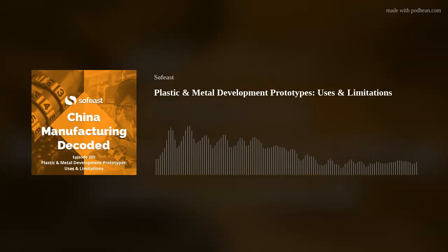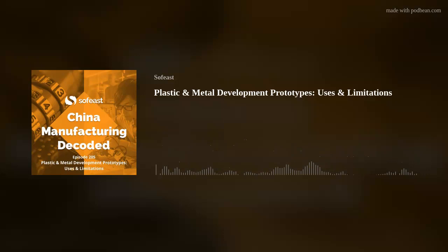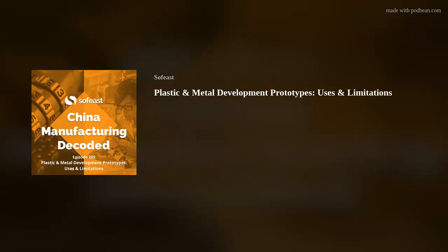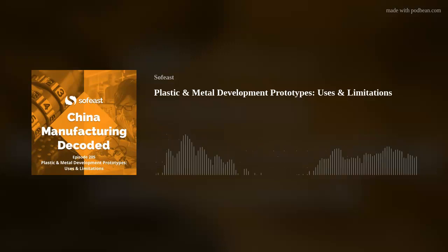So with all of these materials, you need to look at the mechanical properties and say, okay, if I CNC machine it or 3D print it versus my final product material selection, how close am I? What are the limitations I've got to work within? And you need to base your testing through the development stage on the data and information you have at hand. That makes sense? It certainly does.